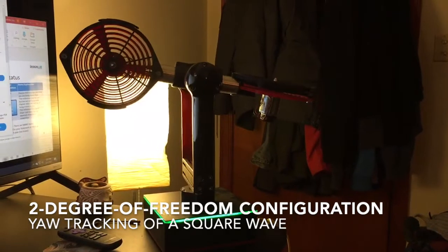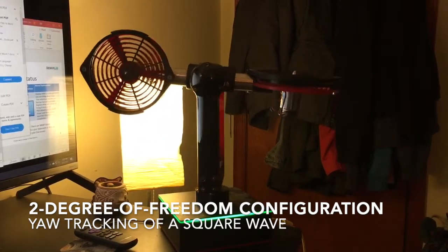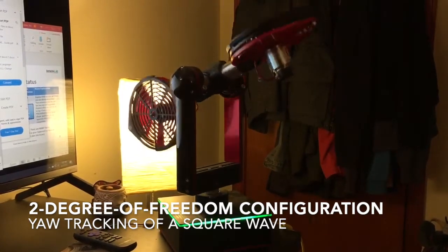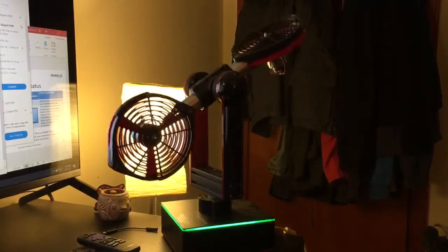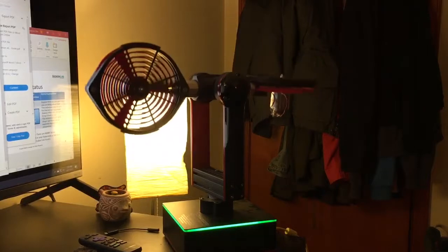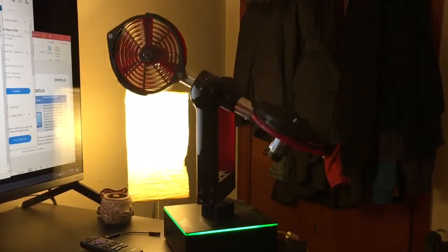Here, the Aero is in its 2 degree of freedom configuration with one of the thruster assemblies rotated 90 degrees. In this example, the Aero is executing a yaw tracking Simulink model that implements a PID controller with a square wave input. The Quarc real-time control software that's embedded in the Aero allows for easy integration with Simulink and MATLAB.